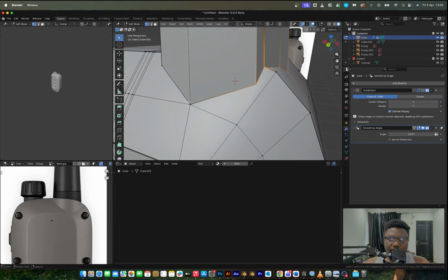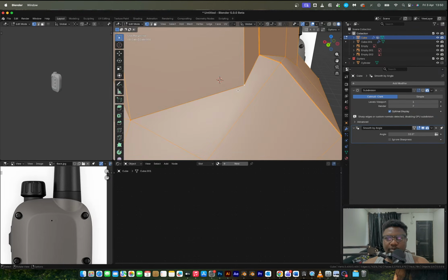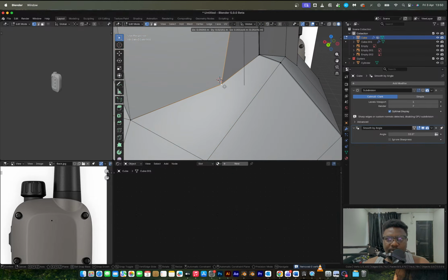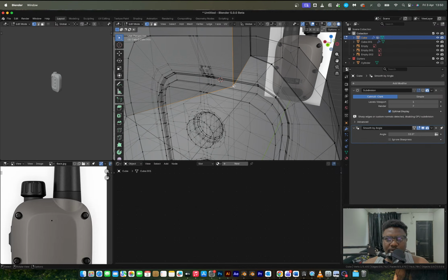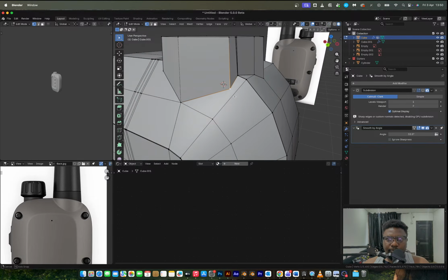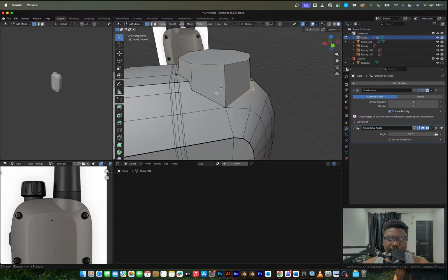Nope. Doesn't mean that I have double vertices here. Okay, I have an unjoined vertex here. So maybe I should do merge by distance first of all, then see what's going on here. Can I add a loop down here, then join this, then do the same with this?